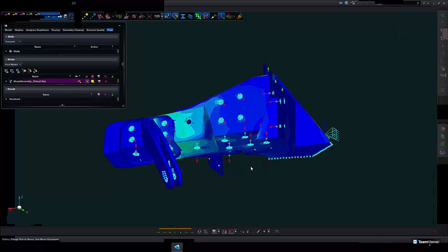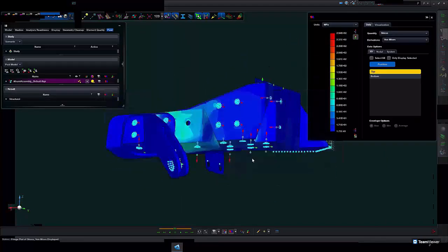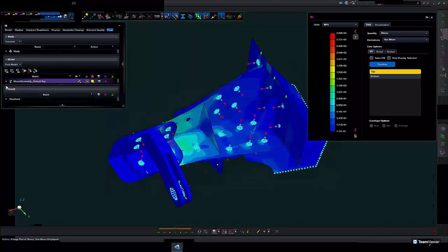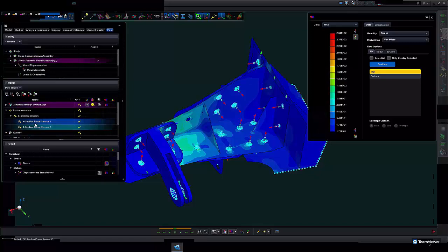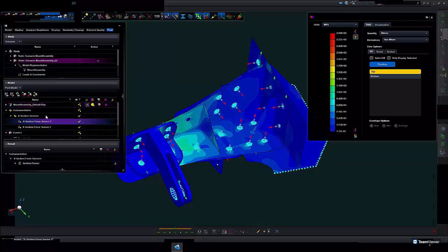Okay, so there are the normal results, and what I now want to show you is a number of things with respect to the sensors. If you look at your sensor, what you need to do is double click in this post model so that it becomes purple, and that then shows the results available at the bottom here and in which format the results are available.